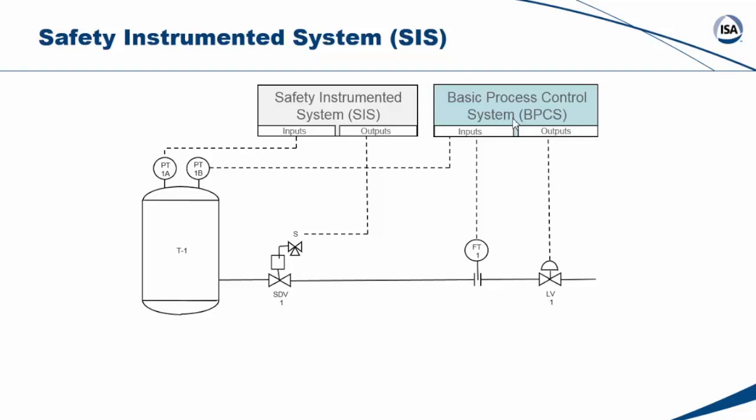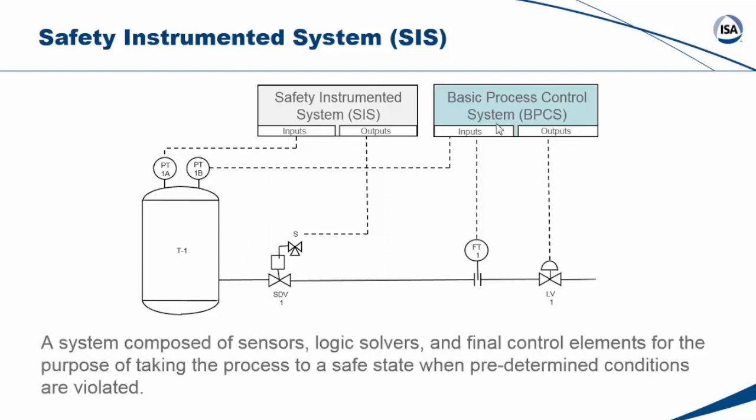Well, in terms of instrumentation, we can have a safety instrumented system, which typically has its own sensors, its own final elements, and its own logic that does not control anything. It just monitors those variables to see if they're outside the normal range, and if so, it will bring the equipment and or the process to a safe state. These systems can be basically any technology, from relays, pneumatics, to solid-state systems that don't use software and software-based systems.